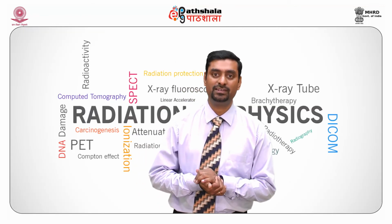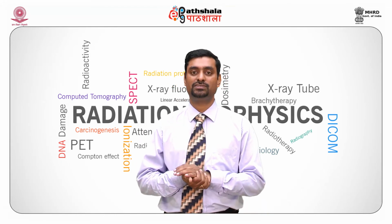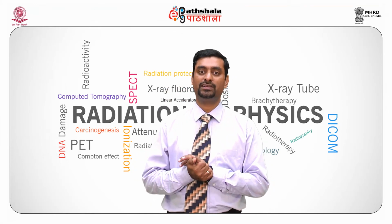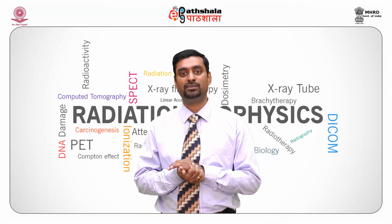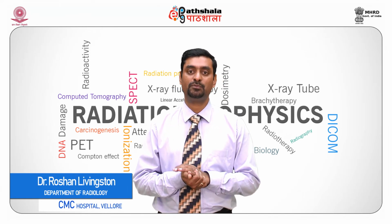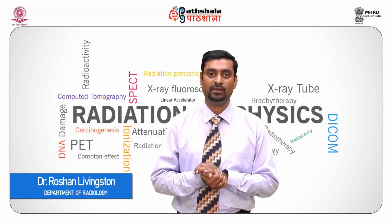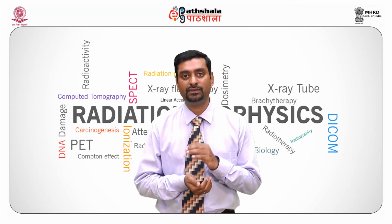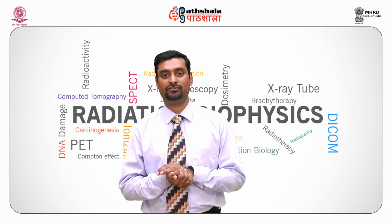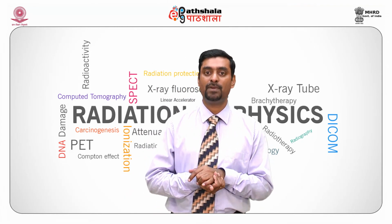This amorphous selenium technology is not indirect because there is no light conversion, and hence it is a direct electron hole pair creation because X-rays fall directly on the detector material. Hence it has high spatial resolution, that means the ability to see two different objects separately. Though the cost is very high, it has superior spatial resolution compared to the indirect method of acquiring images, and this kind of technology is used for mammography.